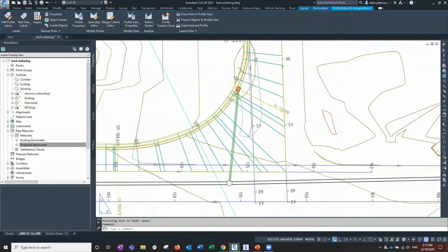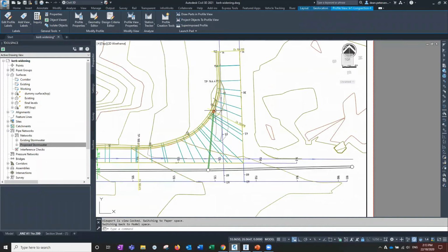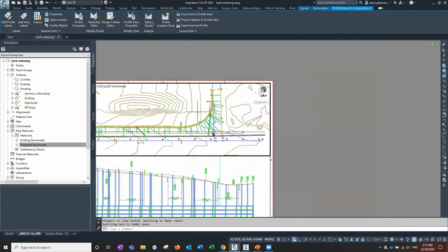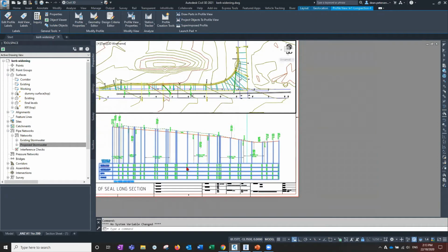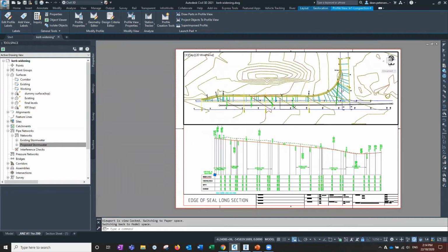So you may want to query the location of that sump. The low point's actually in here, where this little polyline marker is. That's the low point. So very quickly, we can see that we're going to have a problem there unless you resolve that. You might be able to tell that a little bit by the contours, but maybe not. So we've got a good check there as well. I tend to turn those things off when I've finished using them. So some good little easy to use tools that you can start looking at a design that you've been given.